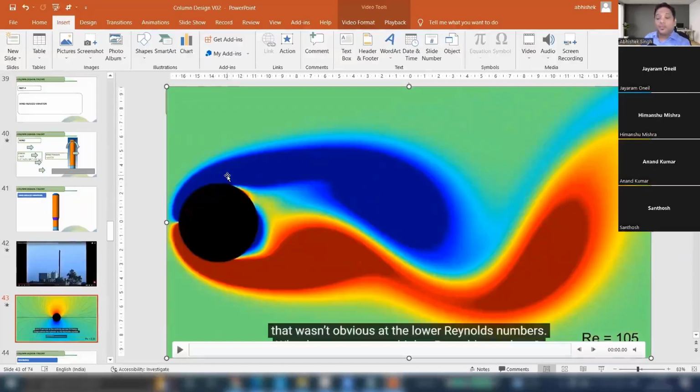Making sense? So the direction of wind-induced vibration is perpendicular to the actual wind velocity. And see that it's creating an alternating force. Because of the alternating force, we have oscillations. I hope you're able to understand now what exactly wind-induced vibration is.